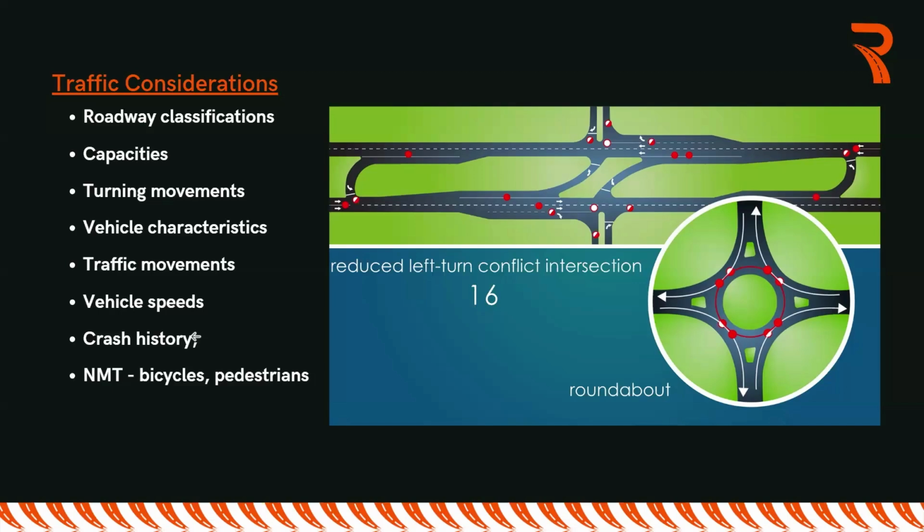And the first one is this one. For reasons of economy, the junction design speed shall not be more than 20 kilometers higher than the average design speed of the major road. So what that is telling you, if the major road has a design speed of 80 kilometers per hour, you cannot say that I'm designing my intersection at a design speed of 100. Now, the second one: for safety reasons, the junction design speed should never be less than 20 kilometers per hour lower than the average design speed for the major road.